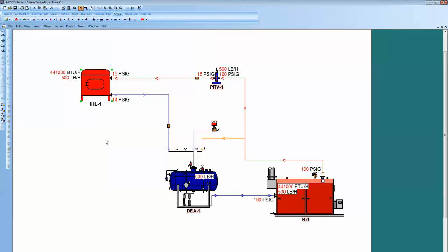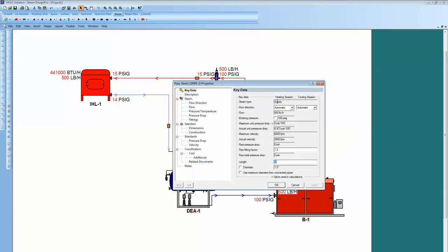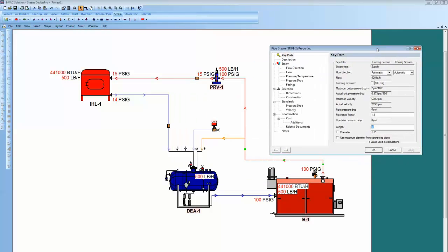Next, let's look at data on a pipe and look at how the software uses equations to size pipe. So earlier we used Spirax-Sarco charts and books as well as ASHRAE to size pipe. And everything here done in the software is per ASHRAE and standard guidelines. So I'm going to double left click on a pipe. Right there you'll see that it brings up information about that pipe.